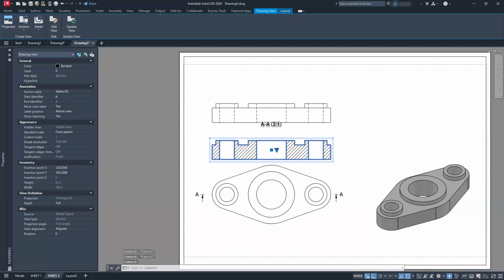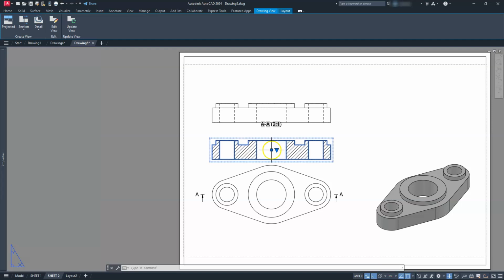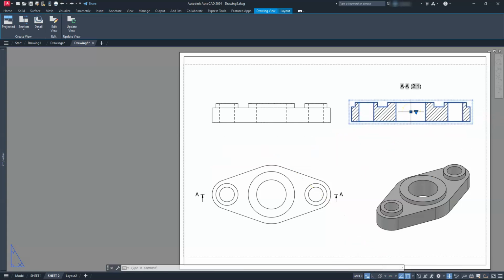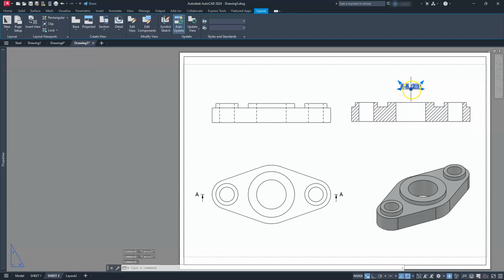And then over here in the properties window is where you usually can break it from, right? So you can see that it has a view alignment here at the bottom. And then if I tell it to break it, so now it's on broken, it will allow me to move this, let's turn the ortho off, wherever I want to. Let's go ahead and move this text below it.